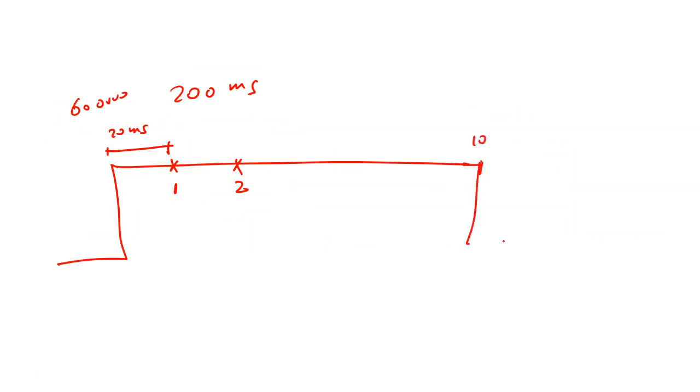At interrupt 10, I have to pull it low, right? So I have no choice. I should have interrupt here, interrupt here, interrupt here. However, now I'm gonna only play in the action. Okay, so I'm gonna say, please, here I'm gonna say, next interrupt after 20 milliseconds. This is my limit. However, the action on the pin, no action.